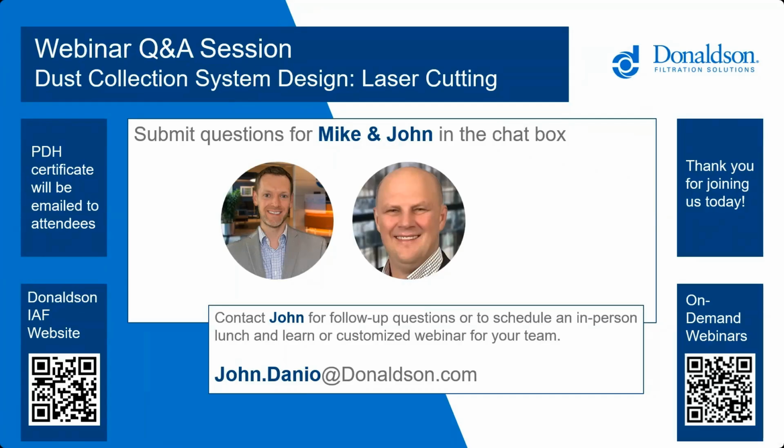Typically, I think the biggest challenge we're seeing nowadays is as the laser powers continue to grow and they cut faster, they cut more material, you run into folks trying to use the same dust collector maybe they used 5 years ago. That may not be an applicable solution for today's lasers. So something you're definitely going to want to look at. So I would say undersizing the dust collector itself would probably be the biggest challenge that we run into.